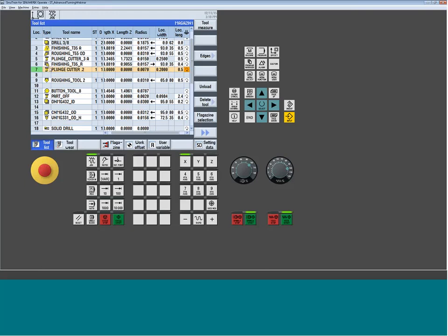Those are pretty cool machines because not only can you swing the tool around, but they're usually on a spindle, so you can flip the tool upside down too. So I could take the same cutter and I could do ID facing operations, OD turning operations. I could flip it upside down and do back turning on a sub-spindle. But yes, the orientation is the same. You just got to know where your base value is when you're picking the correct picture.